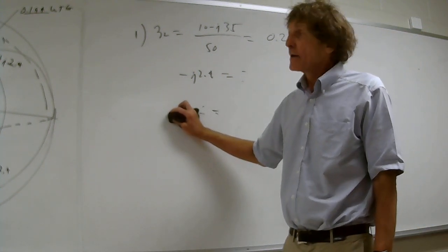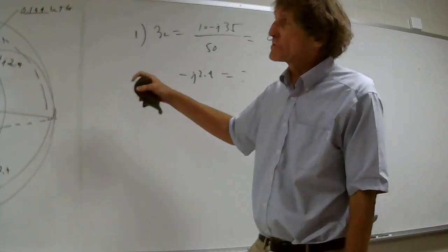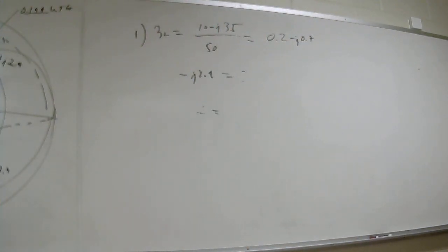You also had to find d. Is d just 0.194 plus 0.5, sorry, minus? You're absolutely right. Let's find d. There's the mile marker we ended at, right? 0.194. Where did we start at? 0.400. That's negative, isn't it? I have to add 0.5. What do you get in terms of wavelengths toward each other? I got 0.294. 0.294, anybody?